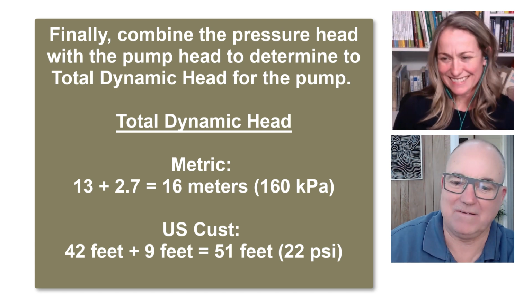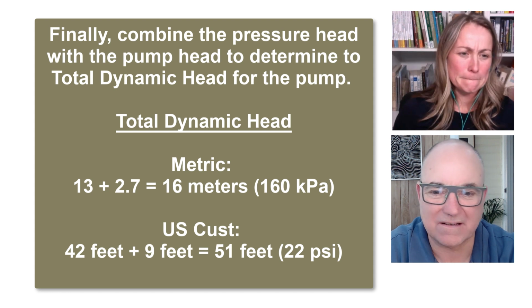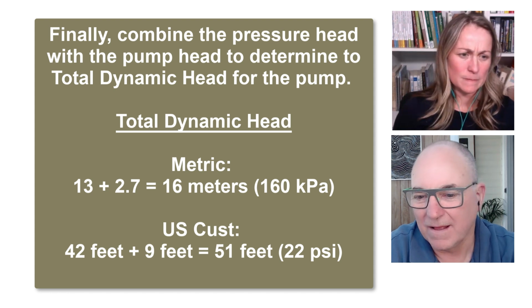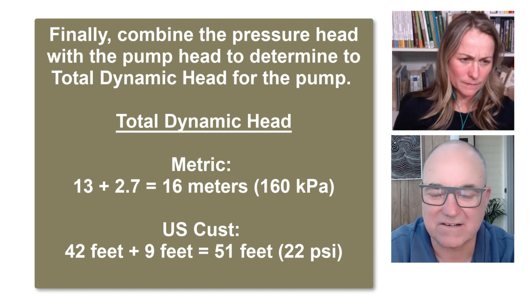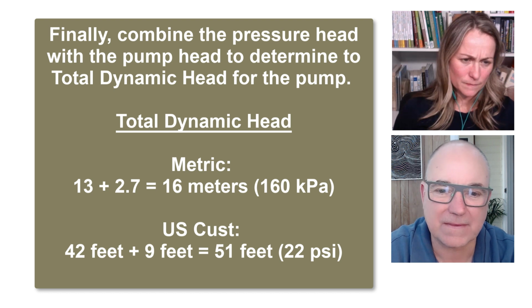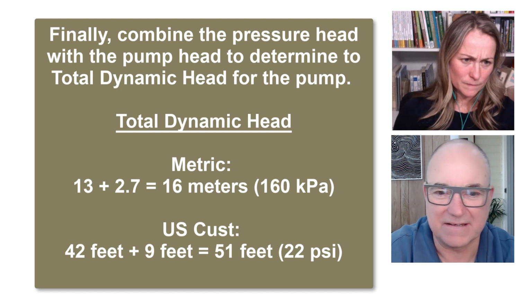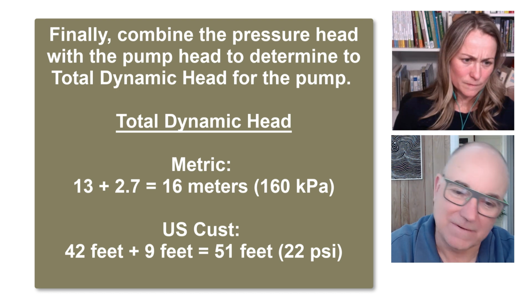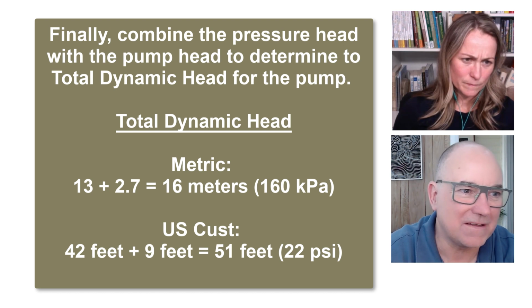Well, it will give people confidence because the students can go through this step by step. This calculation for this situation shows that your normal 300 kPa or 30 meters head, 100 feet head, small rainwater pump is going to supply your situation quite easily.